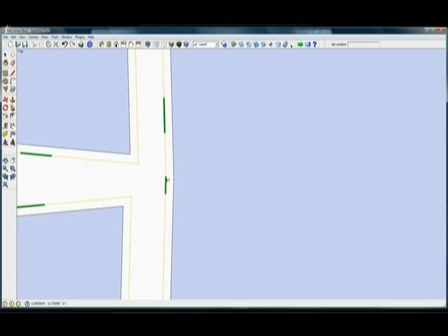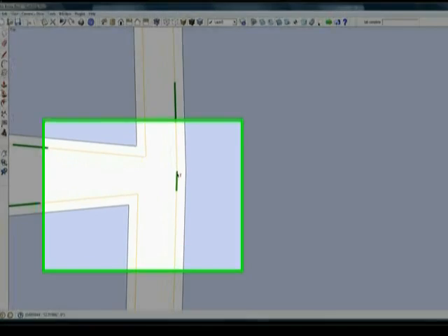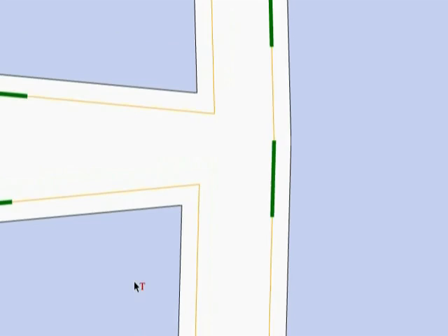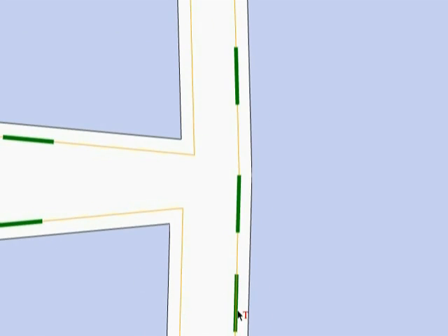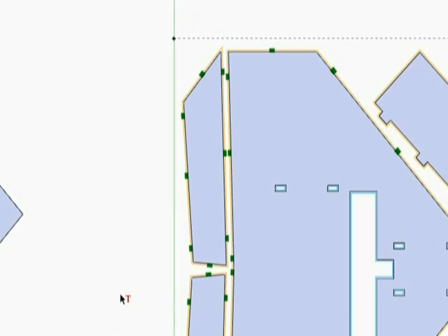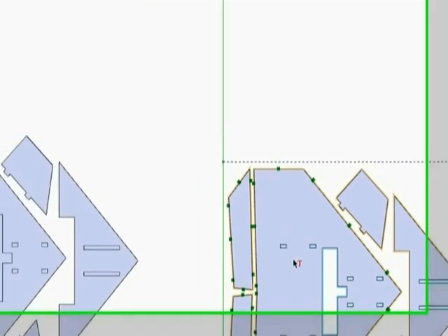In the case of arcs, that's real important, because sometimes you just don't have enough facets to do that, in which case you can go ahead and click on it and then maybe add another one right beside it. And the machine will treat that as one full tab, even though it's made of two smaller ones. So I think with that we will move on to the next.